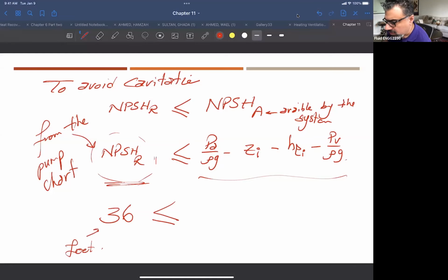So I can multiply by 144. Remember, per square inch, an inch is 1/12 feet, so inch squared is 1/12 squared, which is 1/144, and inch is at the bottom. So in order to convert pound force per square inch to per square feet, we multiply by 144.